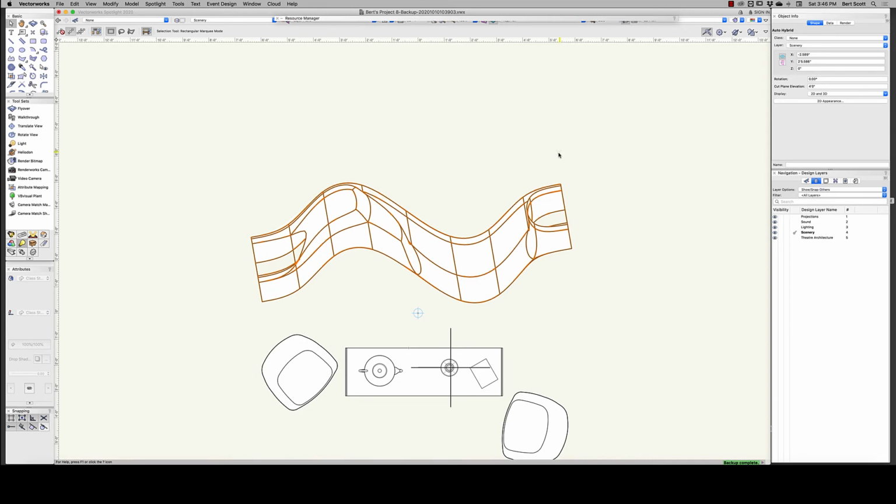So that was an elapsed time of about 5 minutes for it to do that. And unfortunately, we have to do it again. I knew this because the auto hybrid is set to automatically do a section cut at 4 feet above the floor, and there does not appear to be any way to set that in advance. We want to change that to 8 feet 6 because we don't actually want a cut section of this wall, because this is just a mess and doesn't really tell us anything. What we really want is to have a top view of it.